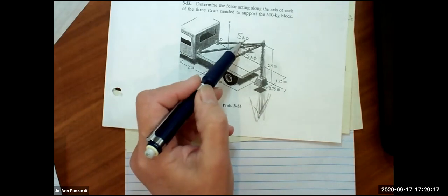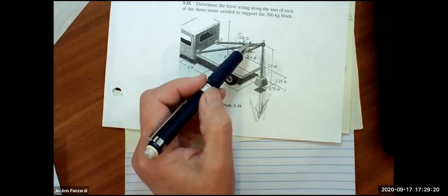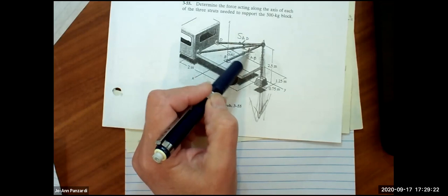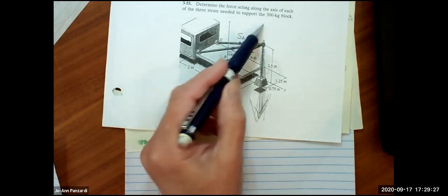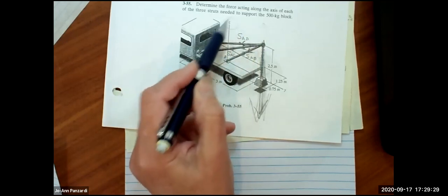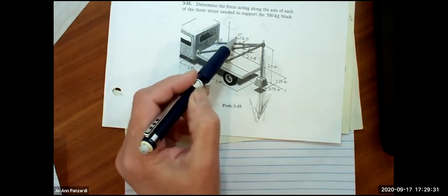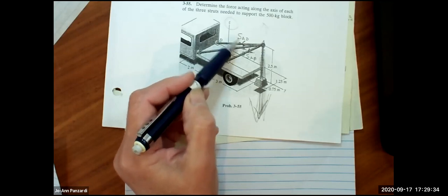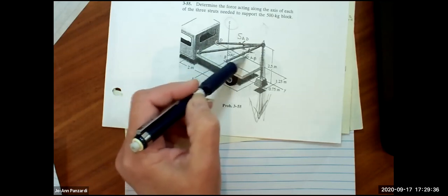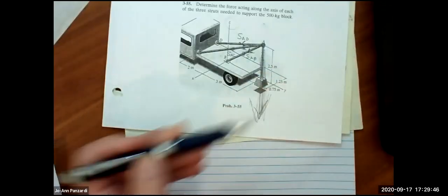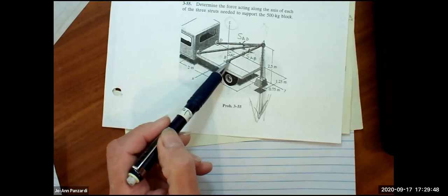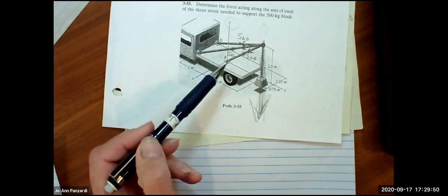Right, that's because I decided to put them all in tension, there's nothing balancing, there's no force going up in the Z direction right now. So what does that mean you're going to get? What values are you going to get for these struts? At least one of them is going to have a what? A negative, to show that it's actually going up. We could take a guess, and Isaac said he thinks it's this one, but we'll check it out and see.